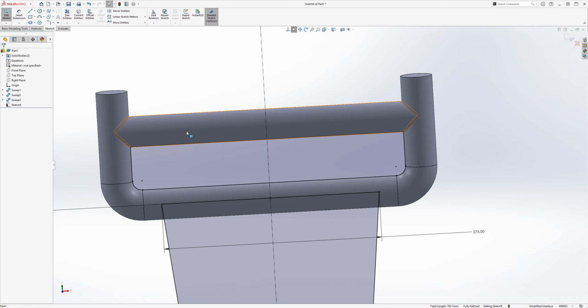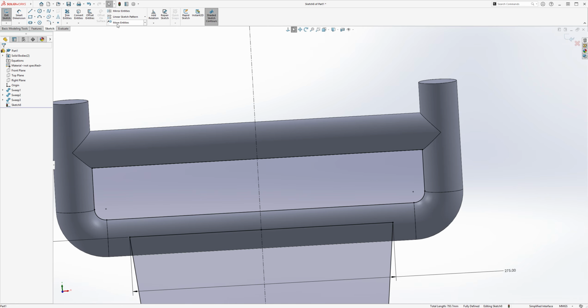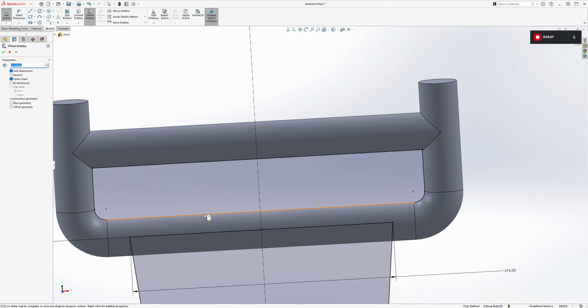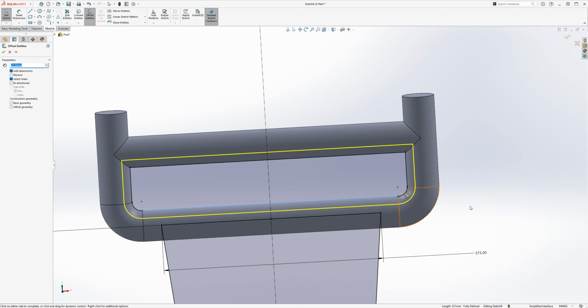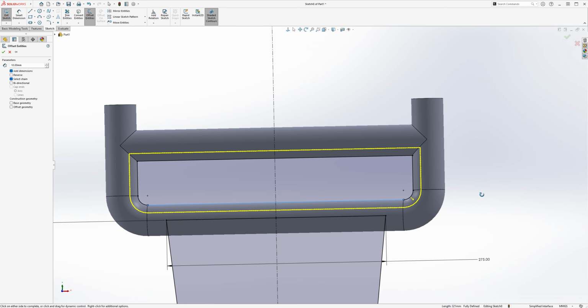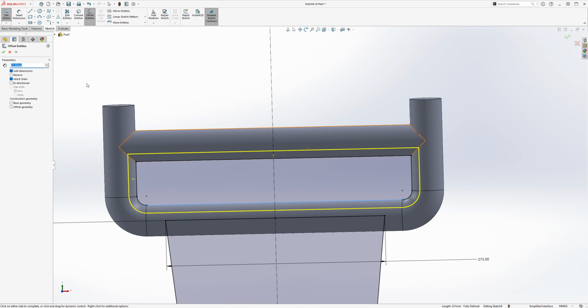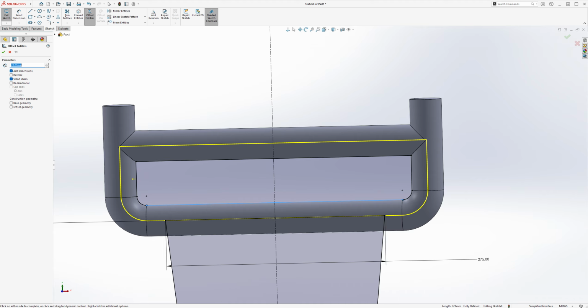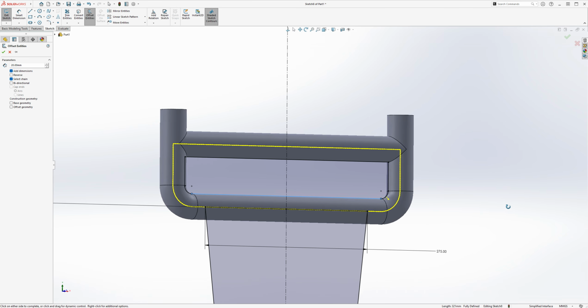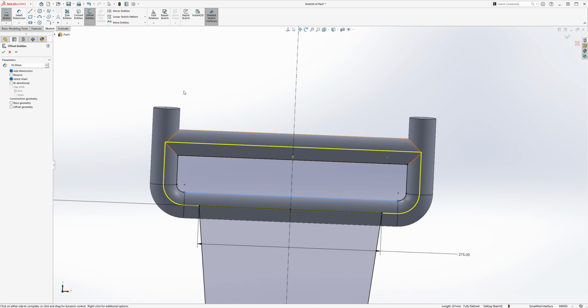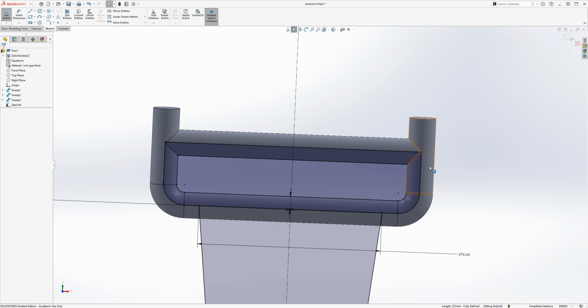So here we need to also intersect this, embed the sketch within this extrusion, and the perfect way to do that is to use the offset tool. So we use offset entities, and I'll select what we just converted, and you can choose any value you want. In this case, does 10 sound good? We might as well go a little deeper, just to make sure. 20. 20 sounds very good. So select OK.